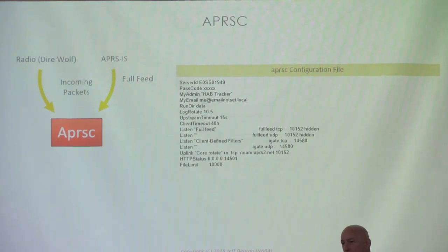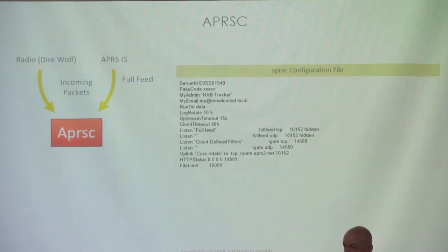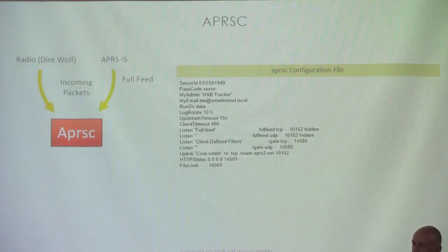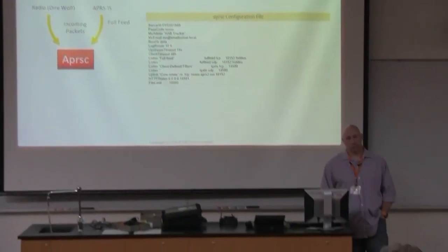Yeah, go ahead. Is that why you're using GnuRadio instead of something like RTL FM? Yes. Since there are a lot of programming APIs, the question was, is that why we're using GnuRadio instead of maybe RTL FM? And the reason is we can programmatically specify exactly what we want from a frequency, and then have control over the whole process with the API. There's a Python API, and I think also a C API that we can interface with. So that's primarily the reason we chose that. The other reason is, if you put multiple frequencies in RTL FM and scan that list, it's sequential. It doesn't do those correctly.